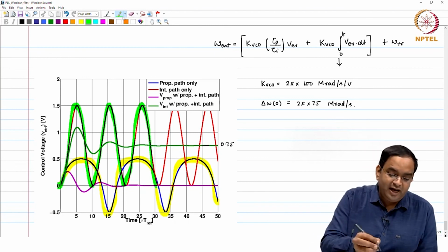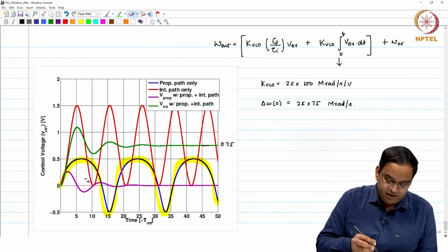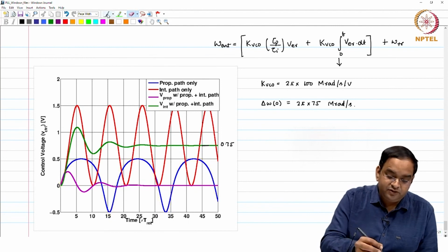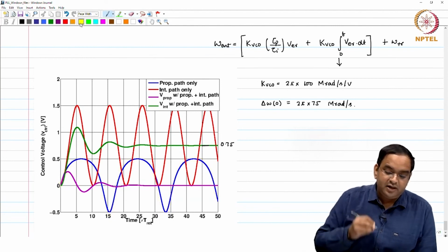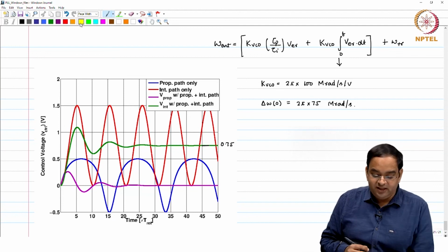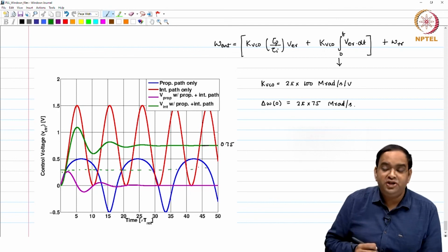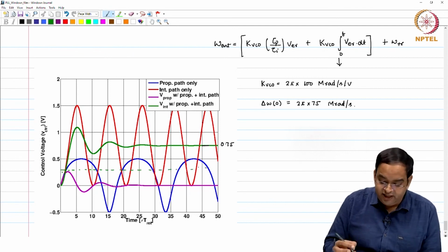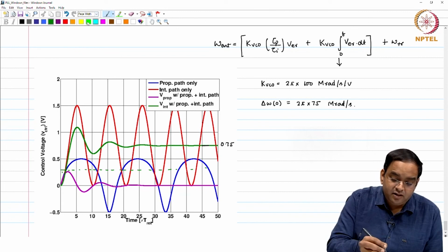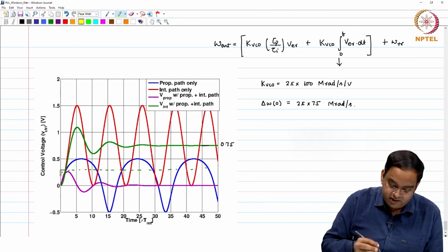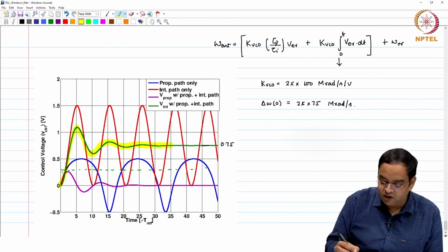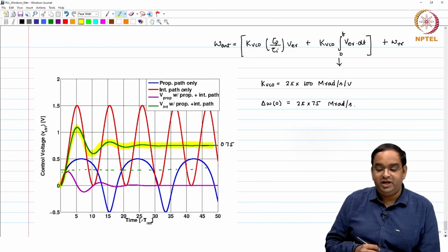Okay. So, that is what happens, but in case we have both the proportional and the integral path, then the pull-in voltage of this asymmetric beat note is actually utilized to integrate and finally achieve a fixed value on the integral path, as shown here.